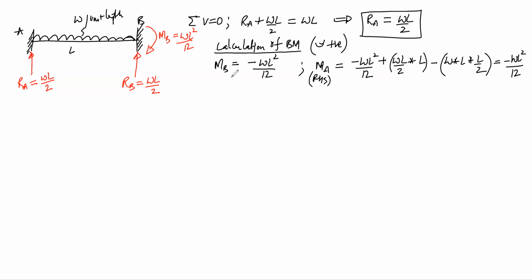So now we can draw the shear force diagram. So this is our reference. At point A, there is an upward shear force of WL by 2. And from point A to B, there is a downward UDL of W over a span of L. So it will be WL by 2 minus W into L, which is minus WL by 2 in the negative region.